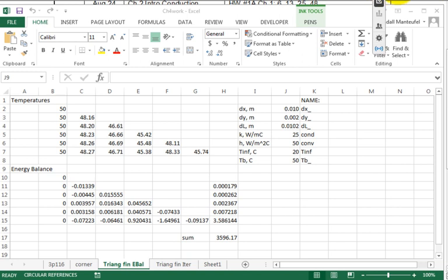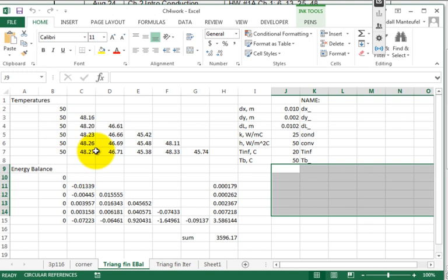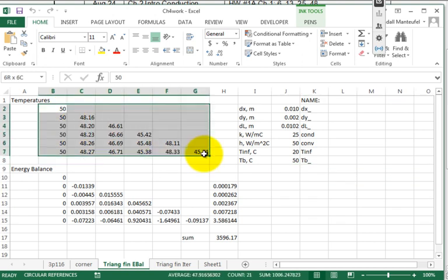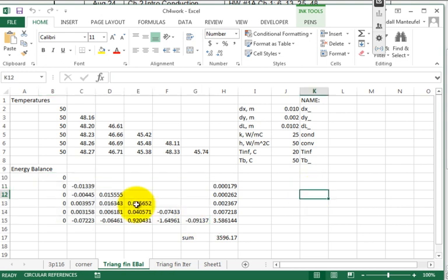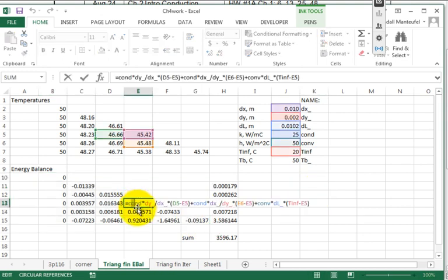All right, last time we were solving this triangular problem, were we not? We were solving for the steady state temperature distribution. And so the way I broke it was I put this triangle up in here. The lower part of that rectangle that I shaded has the temperature values, and then based on those temperature values, I have an energy balance. And what I wanted to do is drive every one of these energy balances, which are based on the temperatures above, to 0.